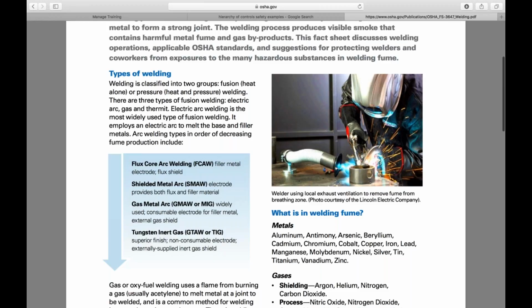Also, we want to know what hazards we may be adjacent to. First and foremost, possible hazards are often going to be utilities. Do we have water lines, lines under pressure for water? Do we have electricity in the area, AC or DC, overhead power lines, underground power lines? What about gas lines? Do we have any natural gas, or any other gas buildup there? Any H2S hazards or methane buildups? The same thing for sewer systems: do we have any sewer system hazards which may pose biological or chemical hazards? And do we have any other utilities or fiber optic lines?